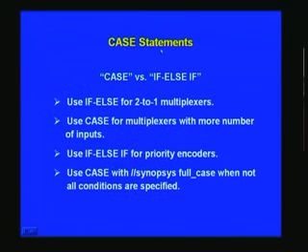Now to summarize and make a comparison between case and if else if, it is listed here. We have already seen that if your intention is to make a 2-to-1 mux, use an always block with if else statement, and if you want more than 2 inputs, you use a case statement. If you want priority encoders, we have already seen if else if, and if you want Synopsys full case or parallel case, use case here. And full case is used when not all conditions are really specified. That's what we have already covered.